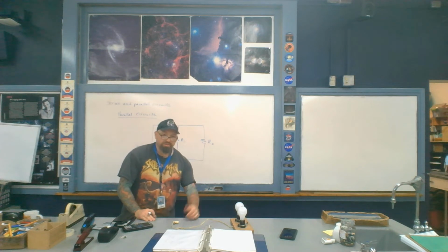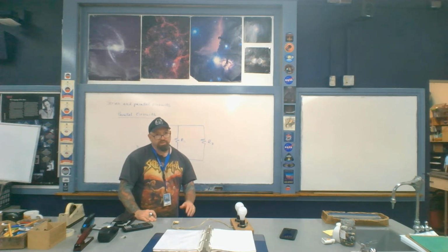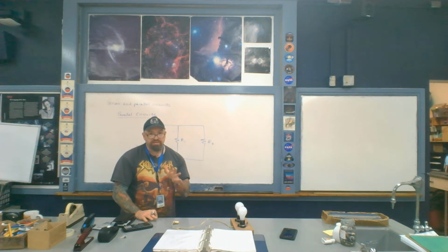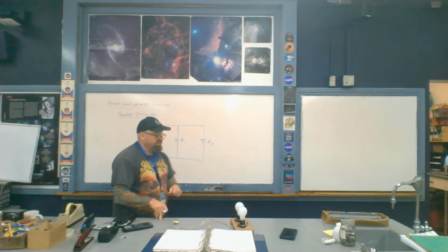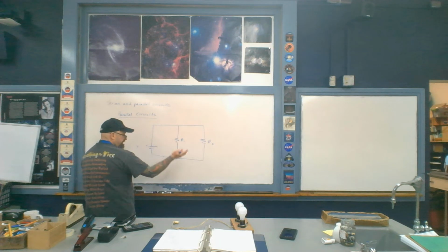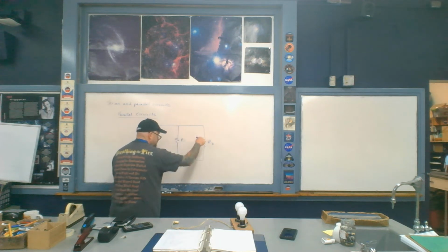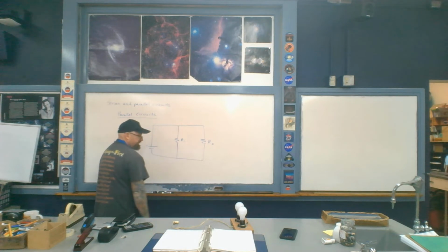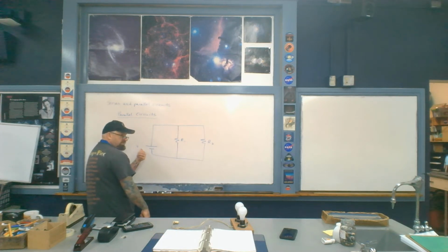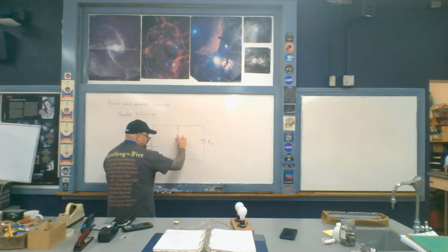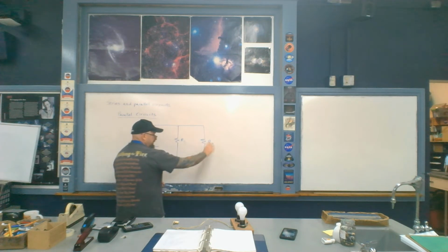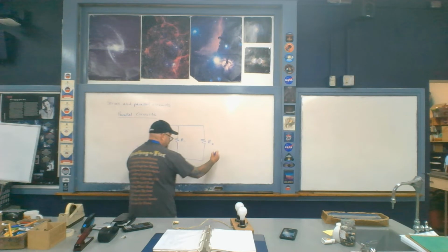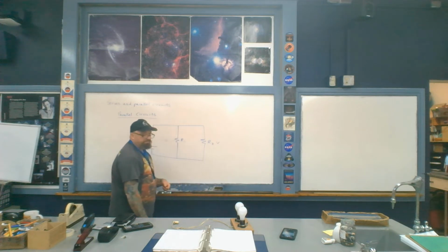Now, as I mentioned earlier back in chapter 25, whenever you draw a straight line on a circuit diagram, you think of that as an equipotential surface. So then therefore, as the current flows, we think of this right here as an equipotential surface, and this right here is an equipotential surface. This then means that the voltage V of the battery is the same as the voltage across this resistor R1. It's the same as the voltage across this resistor R2. So here's a voltage V, and then here's a voltage V.